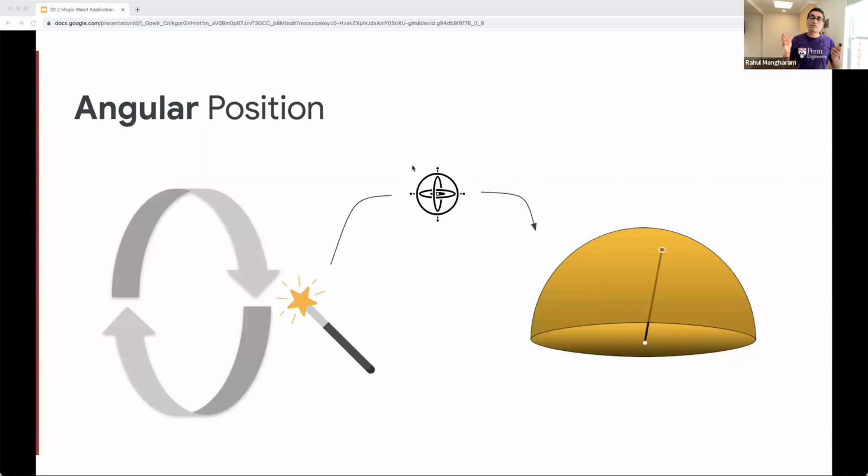One idea is that you can use the angular position, which gives you much higher fidelity in terms of the recording you're making. An improvement of this sort of using angular values that we get from the gyroscope is to be able to map the position of the IMU onto a spherical coordinate system. And this also helps in mitigating the problem with differences in the gesture speed, because we are actually getting the shape and we don't have to worry about the temporal aspect as much.